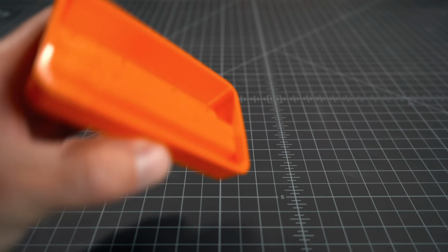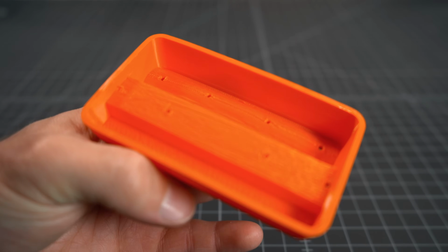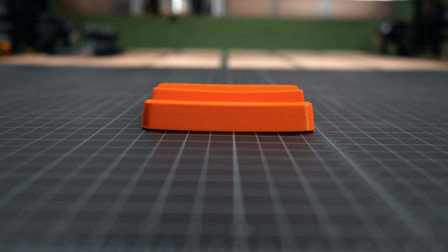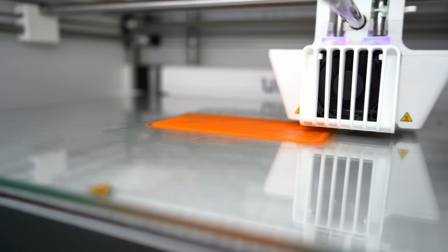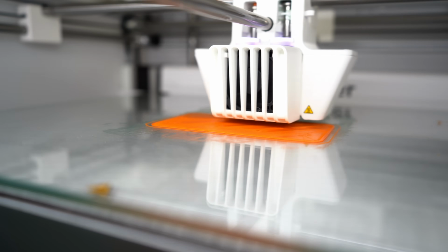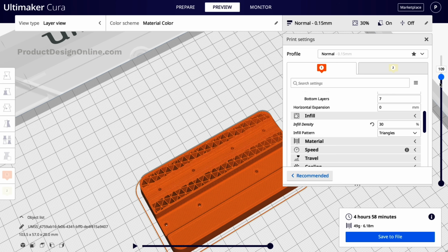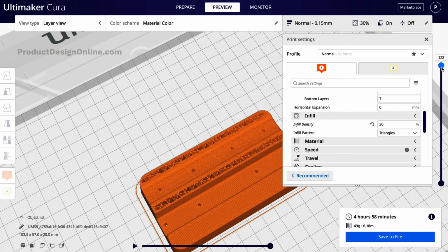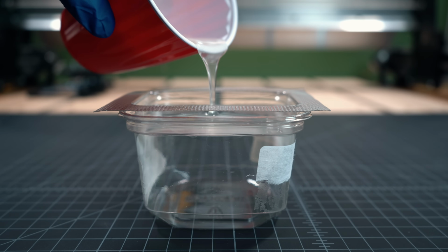At first, I hollowed out the Fusion 360 model to cut down on the print time. However, the temperature of the vacuum former ended up warping the part while the sheet was being formed. Using ABS instead of PLA filament may have helped, but I instead decided to make the model completely solid as we looked at earlier. Of course, the inside of the print only has 30% infill, but it's rigid enough to keep it from warping.